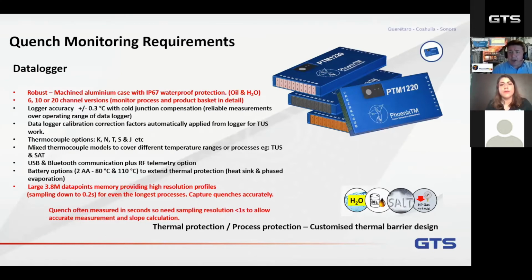As I described earlier with introducing through process temperature monitoring, at the core of the monitoring system, you have a monitoring device, which is often referred to as a data logger. This is basically a sophisticated piece of electronics which allows you to accurately measure, using a thermocouple attached to the product, the temperature where that thermocouple is positioned, whether it's on the surface of the product or in the core of the product, or maybe even in the environment of the furnace. So you can control what you're actually physically measuring if you know where that thermocouple is placed.